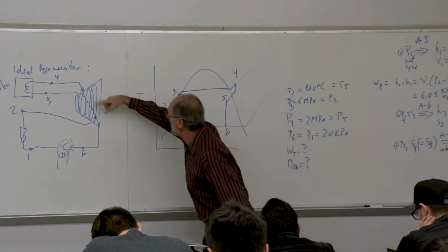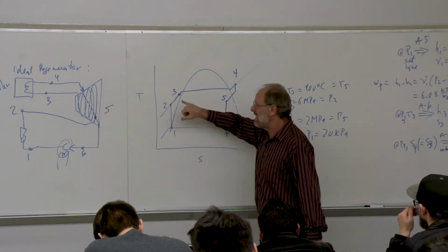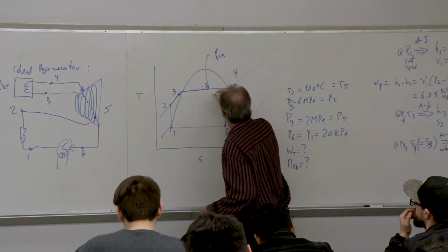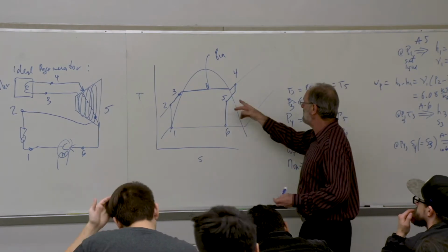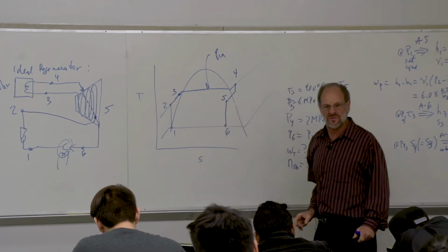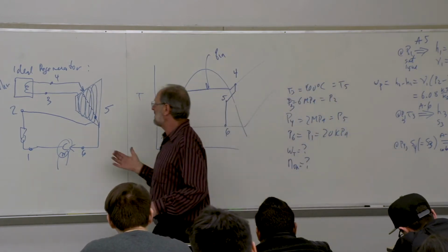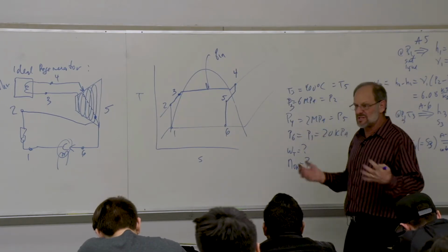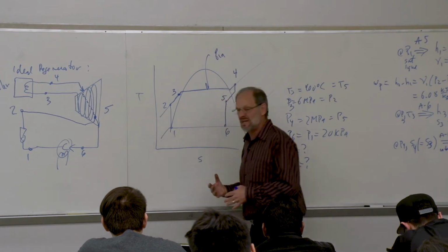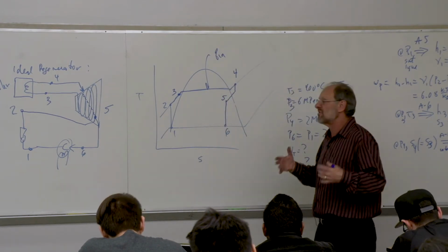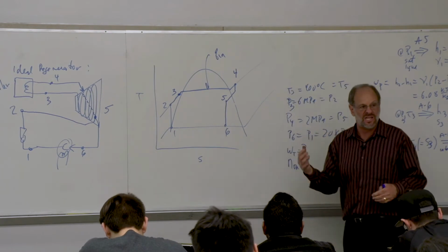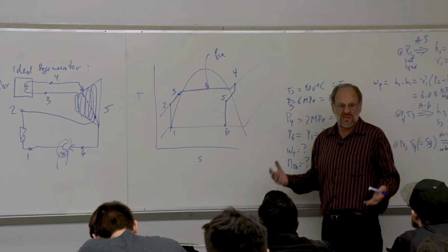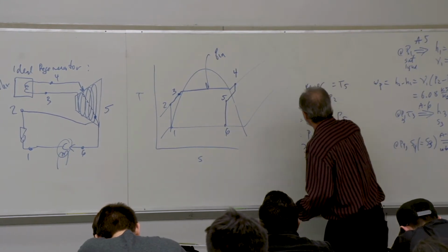We're then taking some of the heat out of the turbine to preheat the water. And then when we add heat in the cycle, the heat input process is only between point 3 and point 4. Okay. Keep in mind that this is another one of those internal heat transfers. When we looked at regeneration for the Brayton cycle, we recognized that the amount of heat gained by one stream is equal and opposite to the heat lost by the other stream, and in a thermodynamic sense, it's a complete wash, so we don't end up with any net heat transfer, right? We also know that our thermal efficiency is only a function of the heat input from external sources, so here we have a lesser amount of heat input. And again, with lower heat input, we should improve the thermodynamic efficiency.